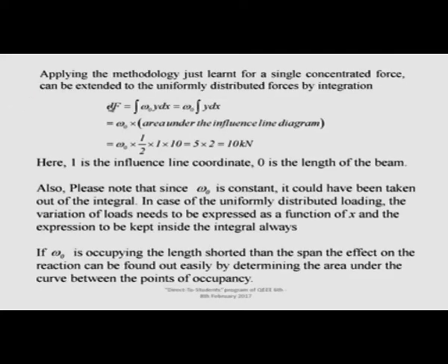When you are finding out for f, the d should not be there in typing, it is a typographical mistake. It is this integration, and the area y dx is nothing but the area under the influence line diagram, and it gives 10 kilonewton.